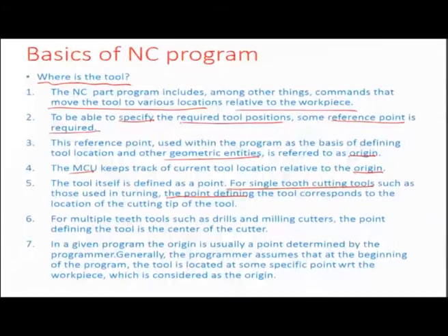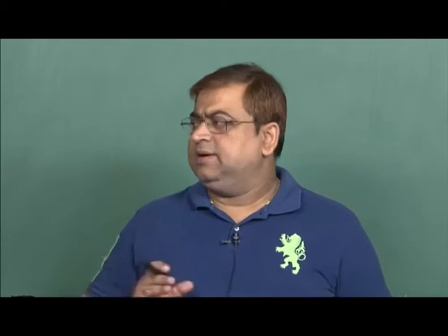For example, look at different drills or milling cutters. In fact, some of the inserts are also present like a circular battery of tools, and so in such cases the point of defining the tool is actually the center of such a cutter, and the cutter has a finite radius. So, the engagement which is taking place at the edge between one end of the tool and the workpiece is at a certain radius from the center, and that has to be somehow compensated